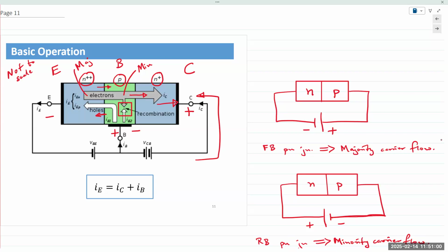If you apply one cycle of a sine wave, 10 millivolts peak to peak, and you have 10 volts between the collector and emitter, now your 10 volts DC takes on the shape of the 10 millivolt sine wave. And so instead of a 10 millivolt sine wave at the input, now at the output, you have a 10 volt peak to peak output.